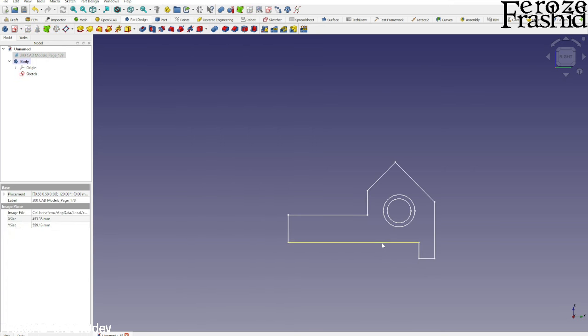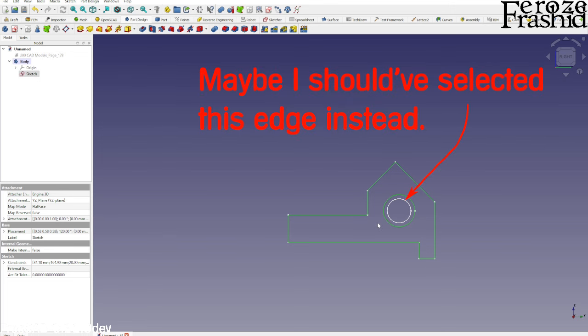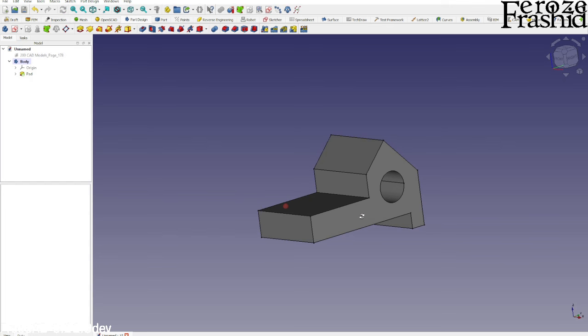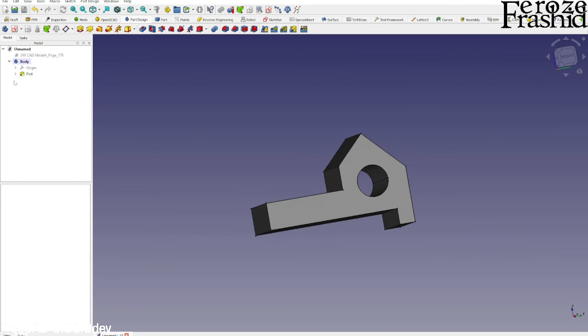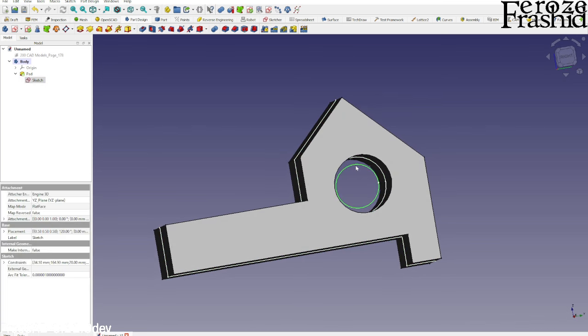But this one, I don't want to do that. What I want to do is select the first sketch that I want to use. Say this is a master sketch, and I don't want to use some lines. I want to select all the lines that I want to use in this step, and then make that pad. So it's 100, I remember, and then it would be symmetric to the plane. And if you open up the sketch, you can see that the inner side, we did not select it, and it was not reflected in our padding.